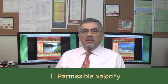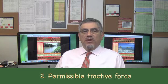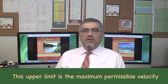Erodible channels are designed using two methods. 1. Permissible velocity. 2. Permissible tractive force. There is an upper limit to the velocity, above which erosion will occur. This upper limit is referred to as the maximum permissible velocity. This velocity is estimated from experience.